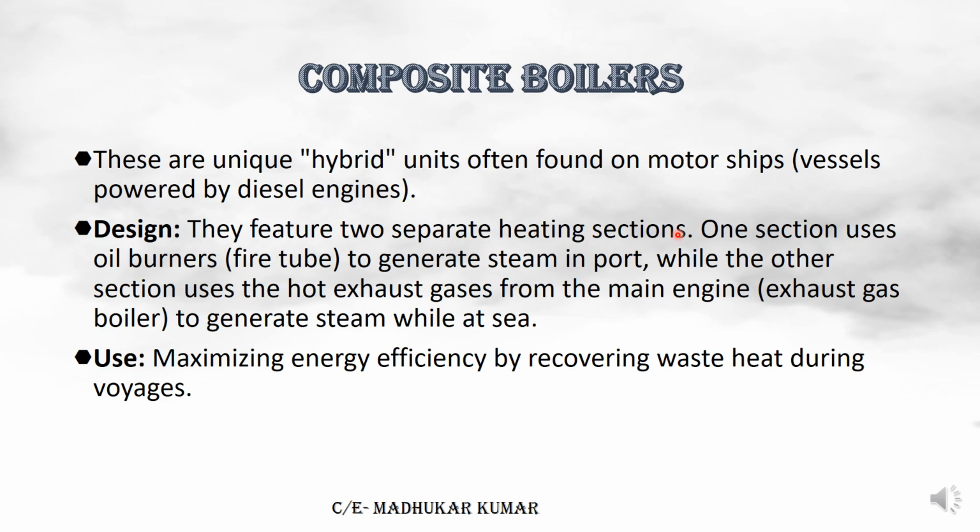Two separate heating sections. One section uses an oil burner, which is in port. Another section uses the hot exhaust gases of the main engine when we are steaming at sea. So it is composite. It is the most widely preferred choice of boiler for bulk carriers and all. So here it is utilized as a waste heat recovery system also.